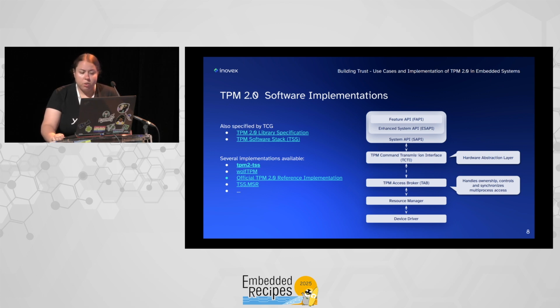and a bit of functionality on the lower level: the TPM access broker, resource manager, and device driver. Whether they are implemented as one thing, or even implemented at all, is a bit up to the use case. Basically, there are several implementations of the TPM software stack. There's a reference implementation by Microsoft. But when working with Linux, it's mostly the TPM2 TSS implementation you will use. I think it's quite good quality and proven software. So that's basically the thing that will be there most often if you're not in the Zephyr world, for example, or the microcontroller world.